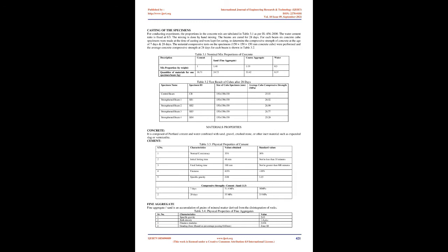and the fibers. The use of side-bonded FRP sheets enhances the shear capacity of the flanged beam, but the strength of FRP sheets to the fullest extent may not be utilized due to the bond failure between the FRP and the concrete. U-jacketing is currently the most popular shear strengthening solution due to its high practicality, but it is limited by end peeling of the U-jacket legs. These drawbacks have opened up a new area of research on the development of anchorage systems.